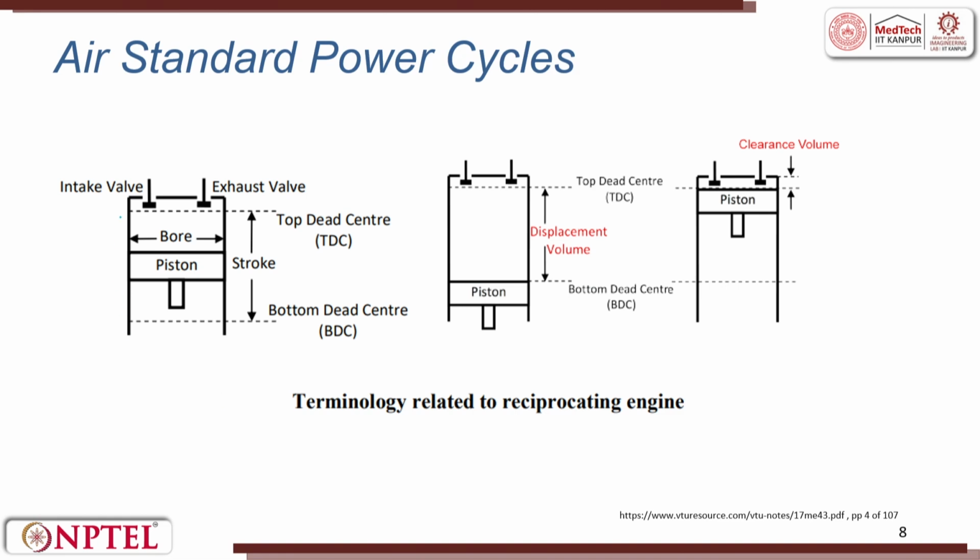This is a cylinder, and the internal of the cylinder is called the bore. Cylinder, the hole, right? You have a water bottle, the inner side of the water bottle is called the bore. Then there is a piston, which prevents the air stored inside the bore from escaping. The piston is a moving member. Depending upon the heat, there can be an expansion, or when the piston moves, there can be a compression. For the air to come into the system, you have an inlet valve, and for the exhaust to go out, it is called the exhaust valve.